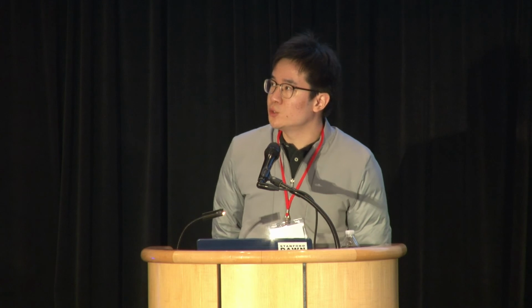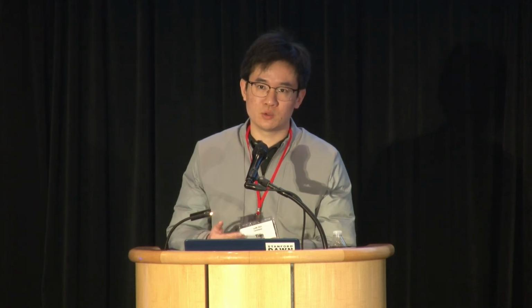And to be more precise, the cuDNN LSTM implementation tries to block on the element-wise operations within the original kernel. But then it still needs to trigger memory transfer when you are trying to send the weights over. In contrast, I think both Microsoft Brainwave and the CGRA that we choose, which is called Plasticine, use low precision arithmetic and were able to embed all the weights on chip. And that's actually a key difference between the Tesla V100 implementation and our implementation, and of course Microsoft Brainwave's implementation.